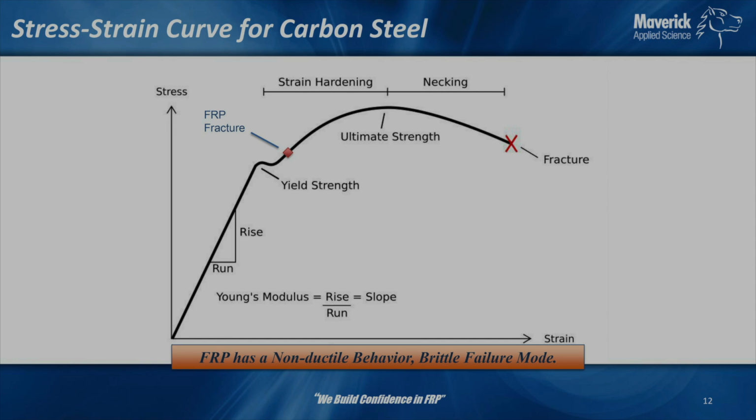So when we're designing it, say this rise over run, this is the area where steel might be, where you have your allowable coming back from yield, your yield strength in steel. Usually something around 2, 2.3, 2.5 is a very common design factor for carbon steel. Well, FRP, we're down here. We're in the design factor of like 6 to 10. If it's tanks, a design factor of 10. So we're nowhere near this. That's why we're not worried about that too much.